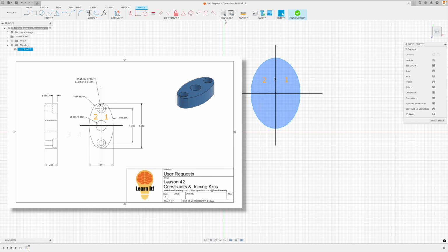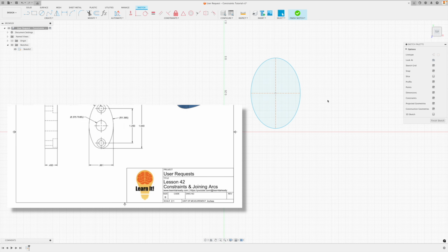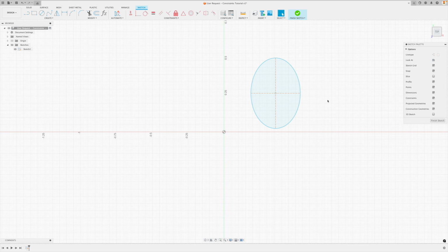And if we mirror these 2 sections down to the bottom, well, they're exactly the same as well. So if we can do that with any kind of part that we're looking at, then we want to design it with the center being the foundation point, the bullseye, or in mathematical terms, we call it the origin. So we want this point to be snapped to or constrained right here.